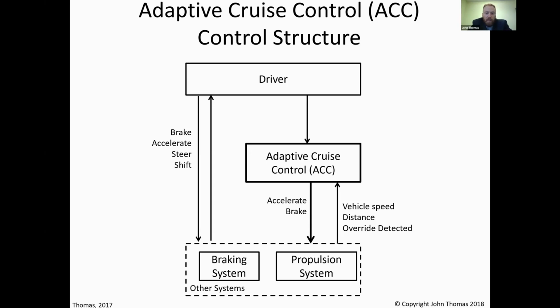Let's look above the cruise control module. What kind of commands would the driver maybe send? Increase speed, on or off, accelerate, yes. So basically what they're doing in the industry is copying all the commands from regular cruise control. That's the first two lines there: on, off, increase, decrease speed, and they're adding a new set of commands, increase and decrease the distance.